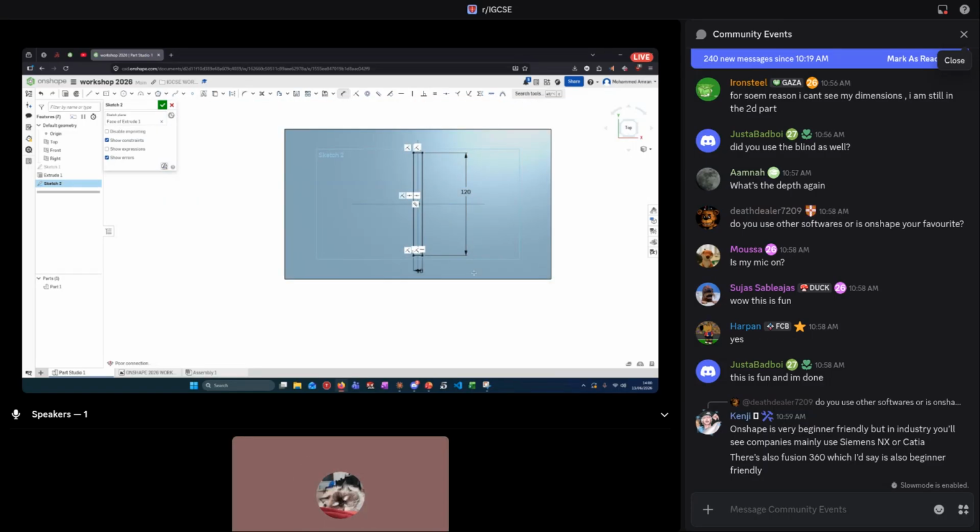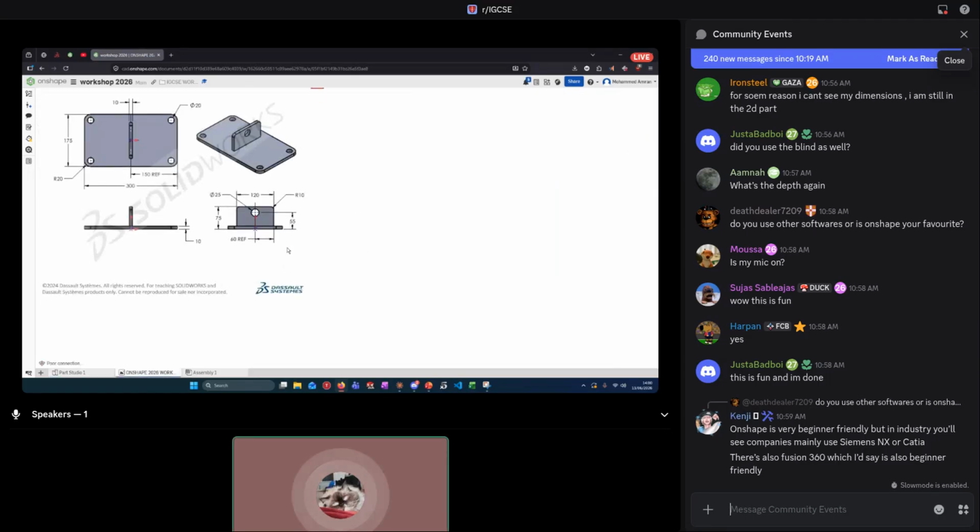Okay. So now once we have the blade part done, we're going to extrude it. As we can see, from the bottom to the top, it's 75 mm. So what should it be from this plane to the top of it? It's going to be 75 minus 10, because this part is 10 mm thick. So we're going to extrude it 65 mm, right?